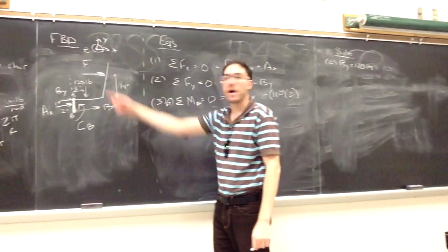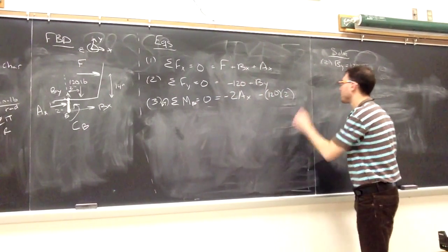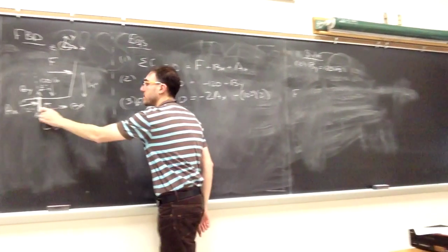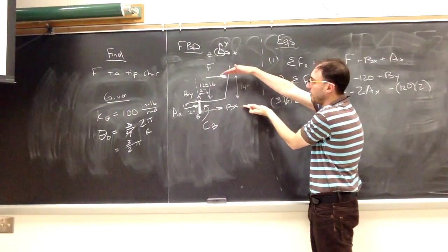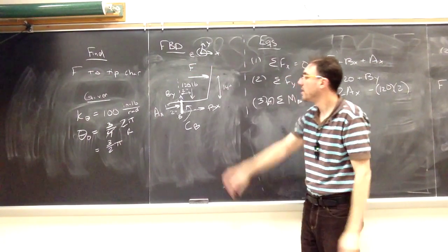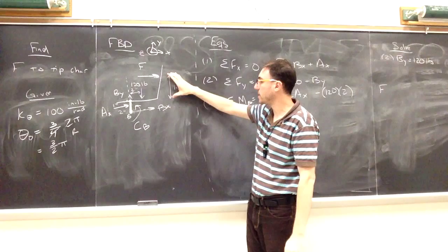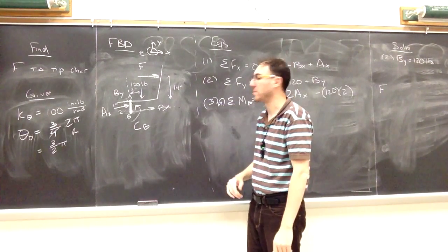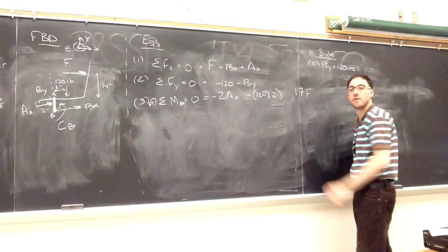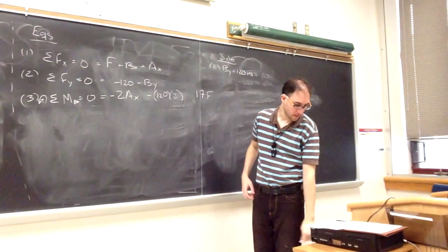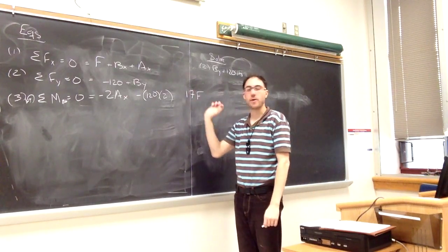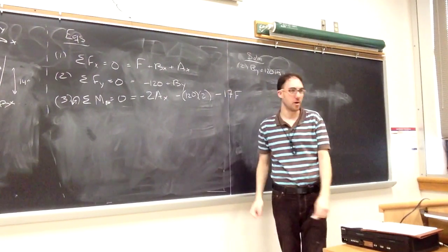And finally, moving up, I have that force F. Its perpendicular distance to point B is going to be this vertical distance. It's a horizontal force, so I use the vertical distance. It's 14 to the bottom of the seat, plus another 3 inches below that to get to point B. So it's going to be 17 inches from point B. And in this case, that is going to create a clockwise moment, so that also will be negative.